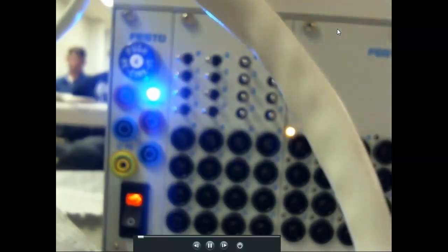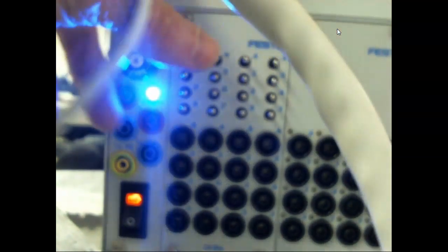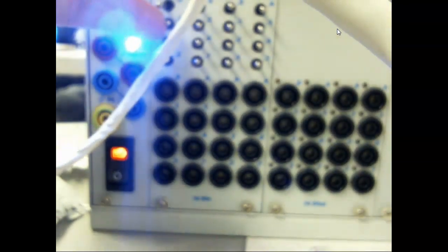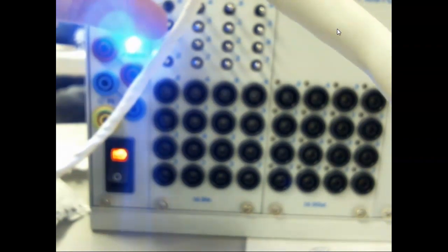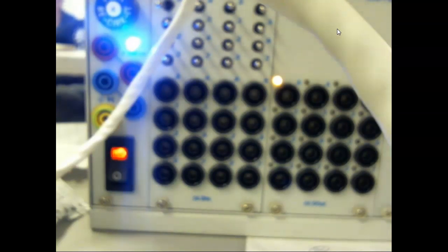So here's my stop button. So let's stop it. What I can do is simulate a normally closed contact by just flipping the switch over to one side. But the output's not on. Then this simulates a momentary contact push button. I just push it and then release it, and you saw the output turn on. But we can also see it up here on the PLC itself. Most of your PLCs have gone back to LEDs now to display if the inputs are true or the outputs are true.